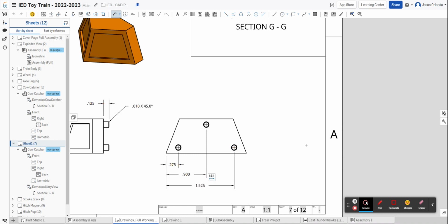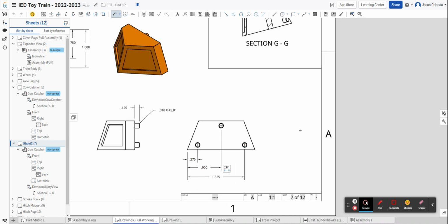And that technique right there would be what's called baseline dimensioning, kind of using that left reference. This is also a datum every time. And now if I want to show the heights of these, I may go ahead and put them over here.